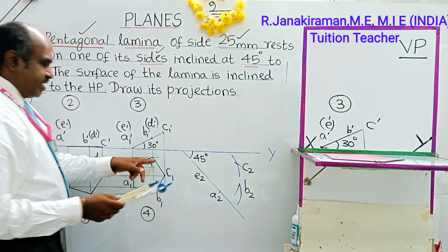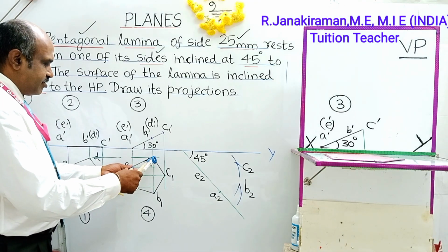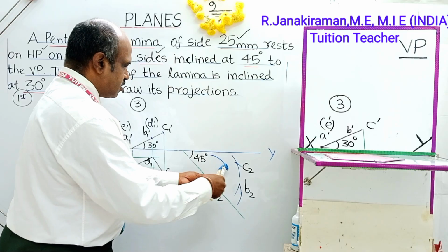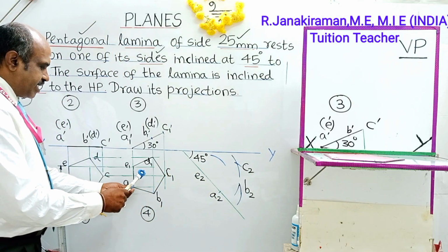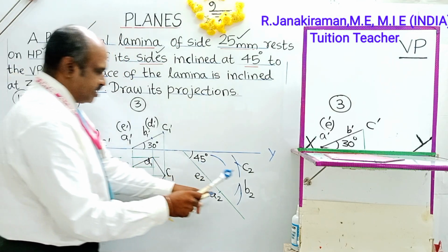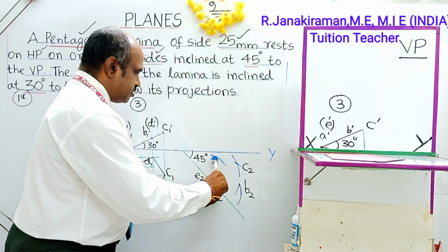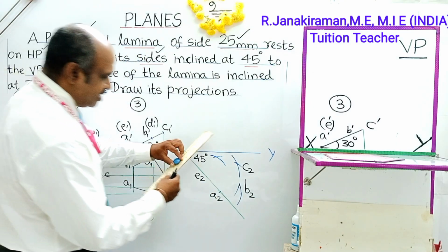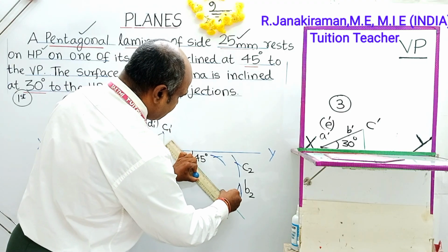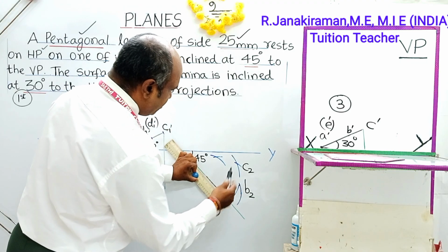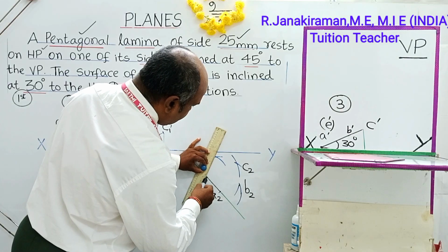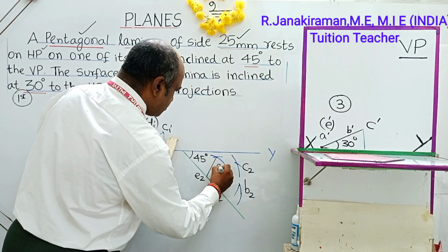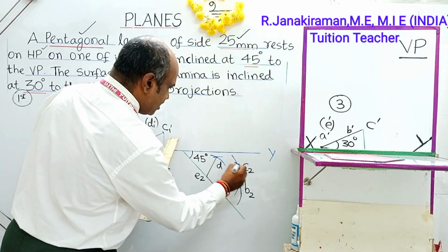Next, we are going to mark D. Take ED distance in your compass. Cut an arc. Next, AD distance is taken in the compass. This is A. Join all those marked points using freehand scale and H or HB pencils. As it is object line, the edges will be visible. It will be dark. So this point of intersection shall be marked as D2. A2, B2, C2, D2.